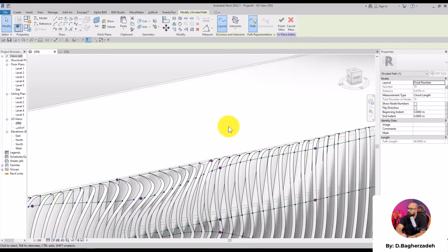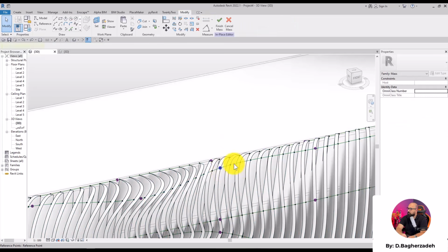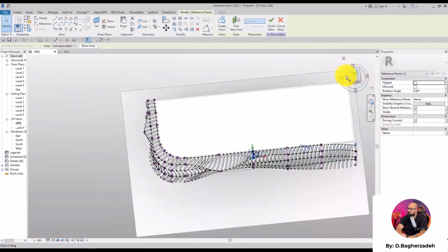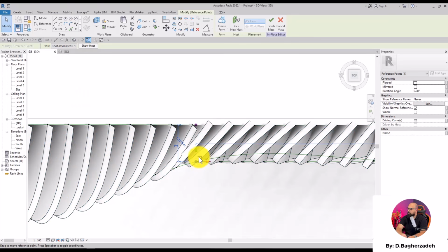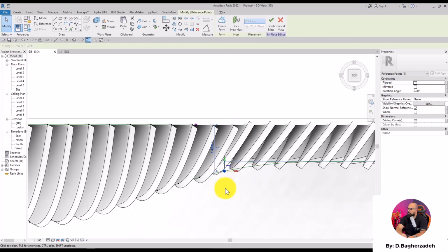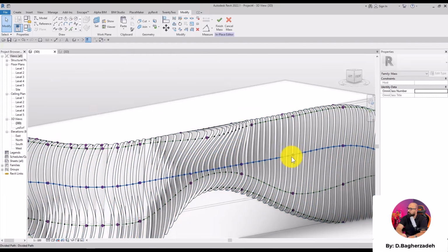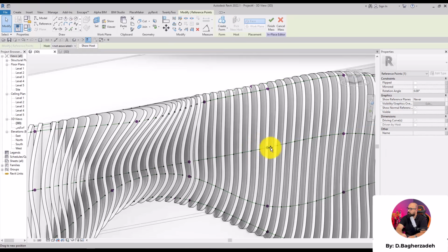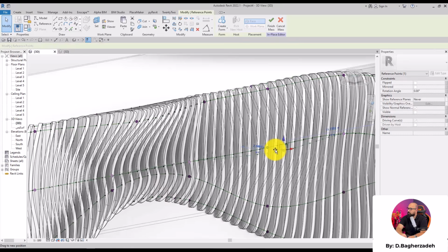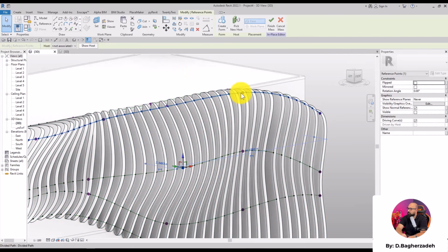I'm going to give you a point. You should try to prevent the profiles from colliding as much as possible. Like, for example, here, as you can see, they are getting closer and closer. To prevent the collision, you can go ahead and then, for example, select this point and, in this case, move it to the right a little bit to make sure that you won't get any collisions in between the profiles. Now, I'm going to try pulling this out one more time. Let's see how it goes this time. Okay, good. Now let's do the same thing for this point up here.